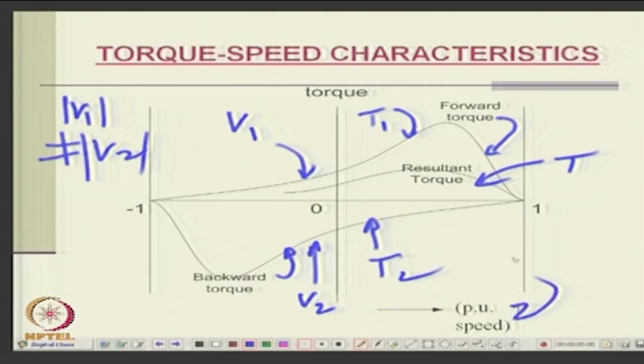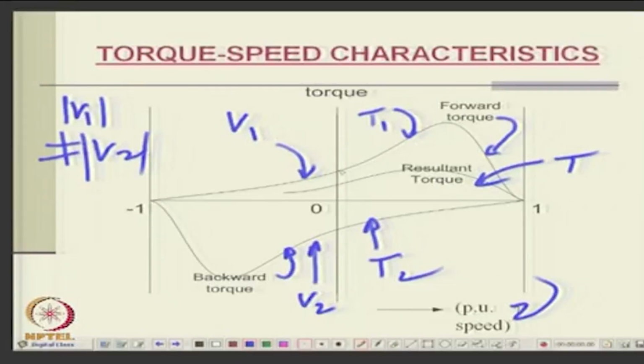Okay. So, an induction machine with unbalanced voltages will experience a resultant torque which is different from the positive sequence torque. Okay. Now, we come to this, when we do this analysis, okay, here the first is only due to V1, another due to V2, and this is due to the positive flux phi 1, this is due to the negative flux phi 2, right.